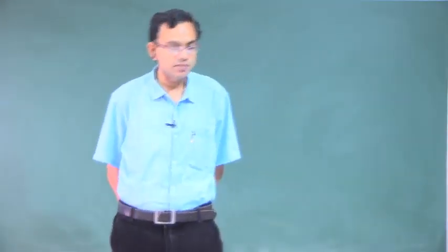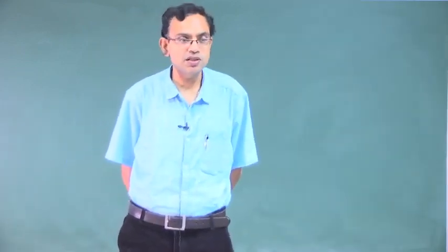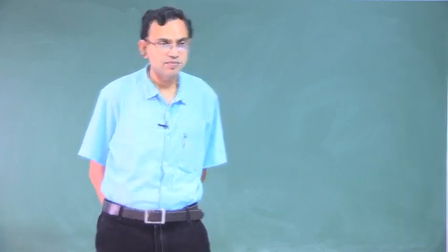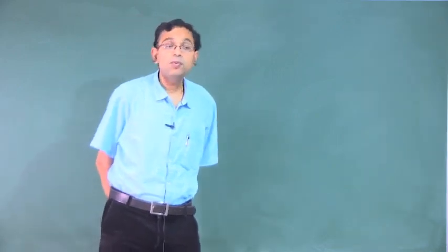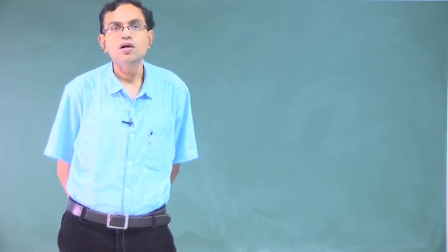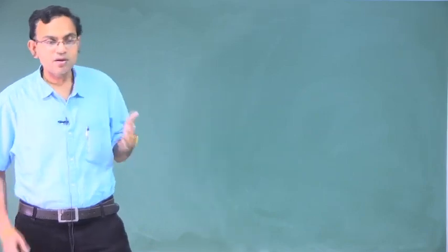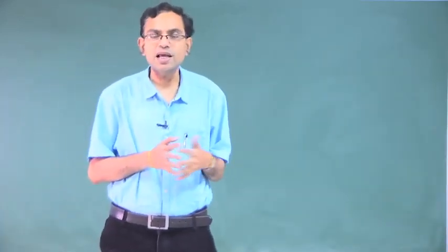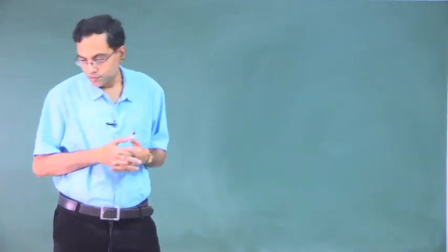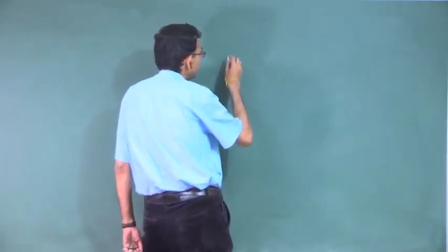In the previous lecture, we were discussing the definition of a complex potential function, which is inclusive of the velocity potential and the stream function. What is the commonality between velocity potential and stream function? That also we need to discuss very carefully. One interesting confluence that we have already discussed is that, except for the stagnation point, they are orthogonal to each other.